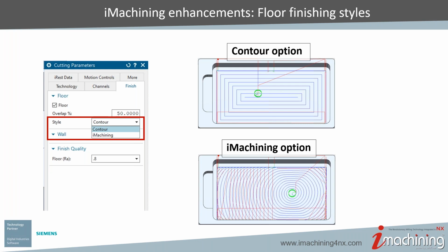And as we know, looking at a lot of parts, especially parts that are going to be used on something visual, motorcycle parts, anything where you see the part, a lot of people don't want to see this spiral looking toolpath. In the end, it's an awesome cutting toolpath, but it's maybe not the most aesthetic toolpath. People like to see this contour style strategy that offsets from the wall, and it just has that neat machining look. You look at it and everybody knows, oh, that's a machined part.